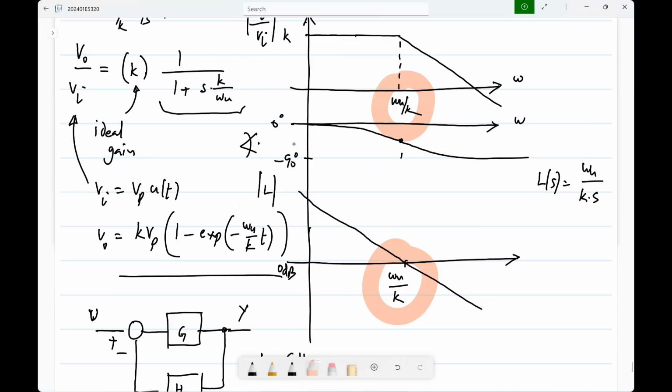Okay. Now, of course, the loop gain is falling gradually from very large values to 1 and then smaller than 1. But if you had to put a dividing line between loop gain is significant here and not significant there, that's the unity loop gain frequency. So the unity loop gain frequency will be roughly the closed loop bandwidth of the system.